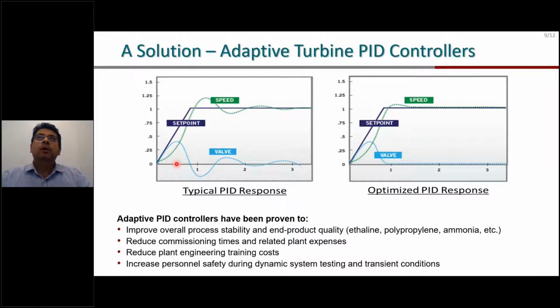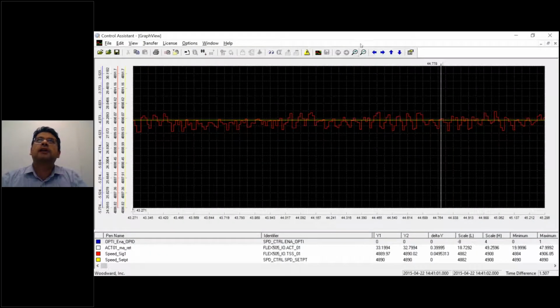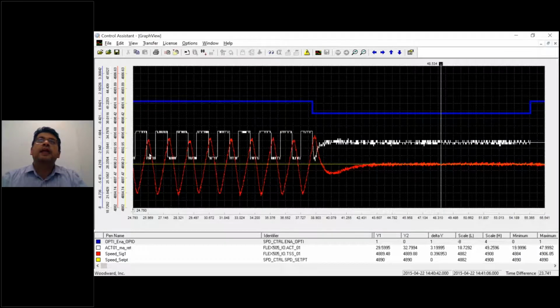So when we use an OptiTune capability or adaptive PID tuning, you will reach your optimum performance, because as you can see, it's very hard to do these step changes, the ones that we represented earlier, manually. It's done on a computer basis, in the controller itself. So these steps are done by the controller, and the controller has some safety in it. If, for example, one of these steps causes disturbance within the environment, it will quit the changes and go back to the old values.